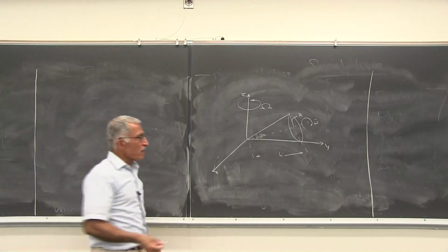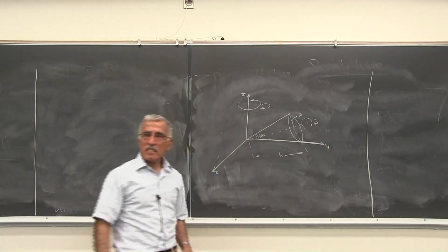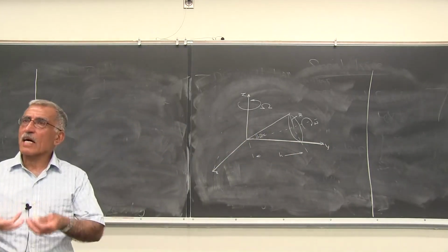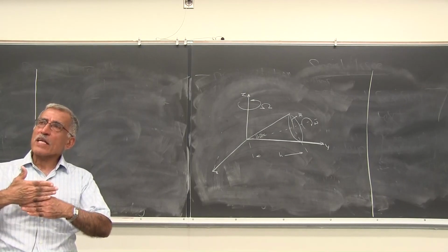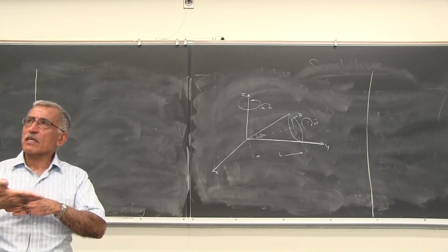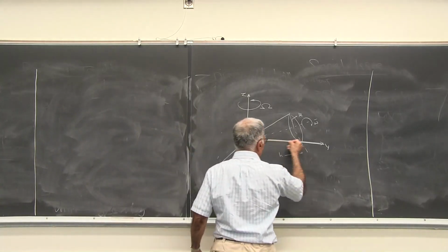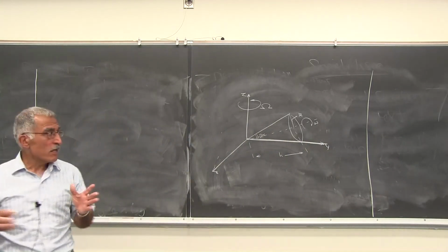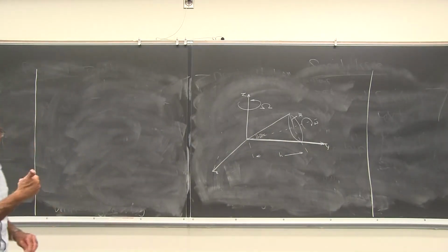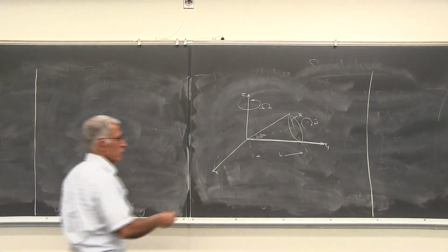That's correct. All of the points that are in contact, as he said, it is basically like peeling a banana. When you are trying to peel a banana, all of the points have zero velocity, and then they get separated. So the instantaneous axis of rotation is here. In other words, your total omega vector, although it looks different, you do have this omega and you have this omega, but the summation of these two vectors must be in this direction.